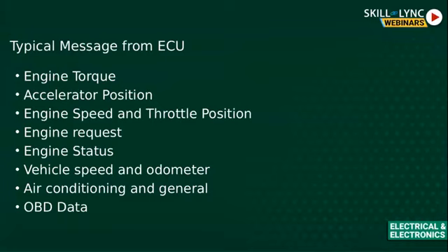so that you get a feel of why we need sensors in a car. Starting with the mass airflow sensor, it is used to measure the air density to calculate the amount of fuel that is required to burn. Next is the spark knock sensor, which is used to ensure fuel is burned smoothly. The manifold absolute pressure sensor monitors the load of an engine.